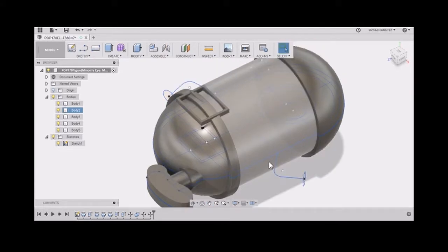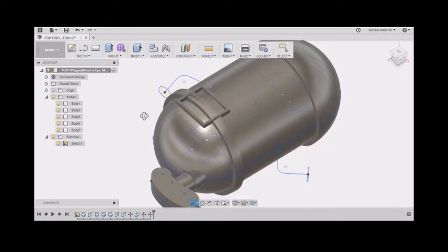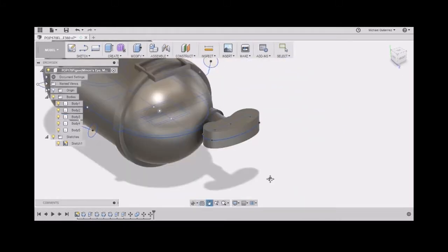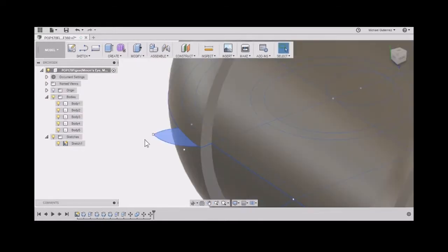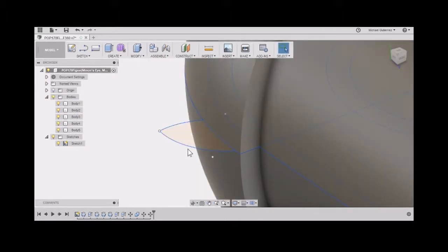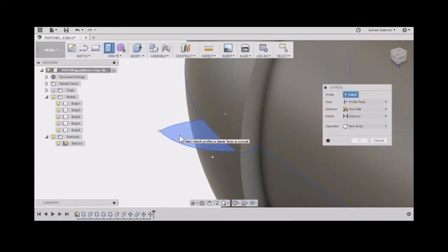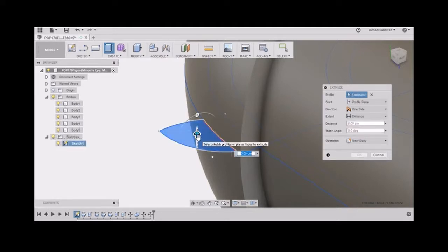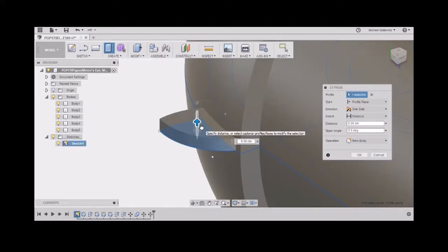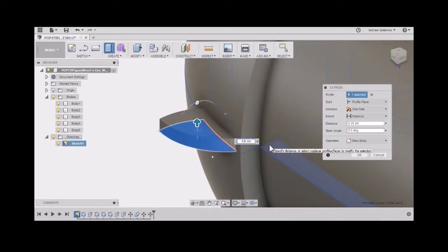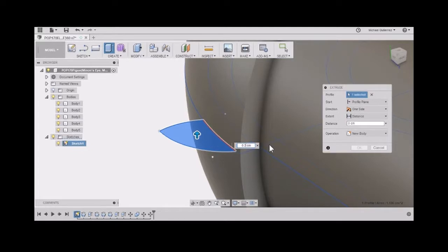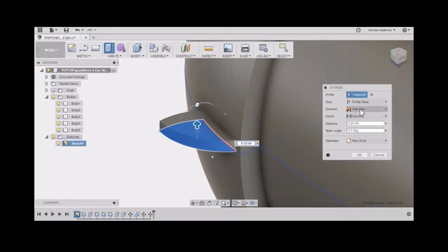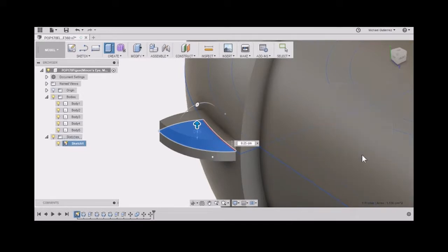So now that we've done that, next step is going over here, this part. So this part's going to be a bit different. First, we're going to do extrude, not so different from what we did earlier. Going up, I'm just going to go up by 25. So manually type in 0.25 and symmetric, and again not so different. New body and hit OK.